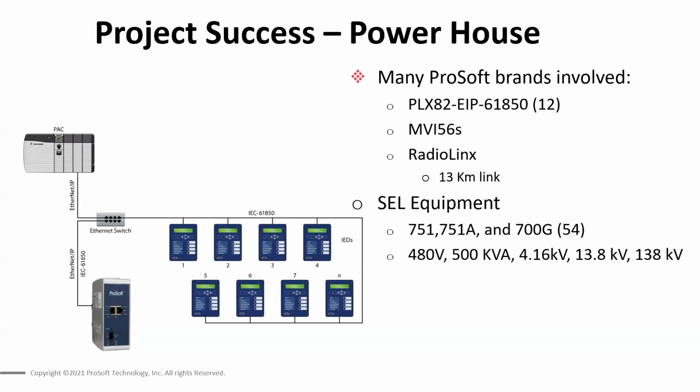So another question came through: is local mounting with the CPU and remote mounting in an I/O rack supported? It is supported. There's a recommendation to use EN4TRs because they support double data rate on the backplane. We'll have some documentation on architectures for both local and remote mounting, as well as some considerations on the ControlLogix side.